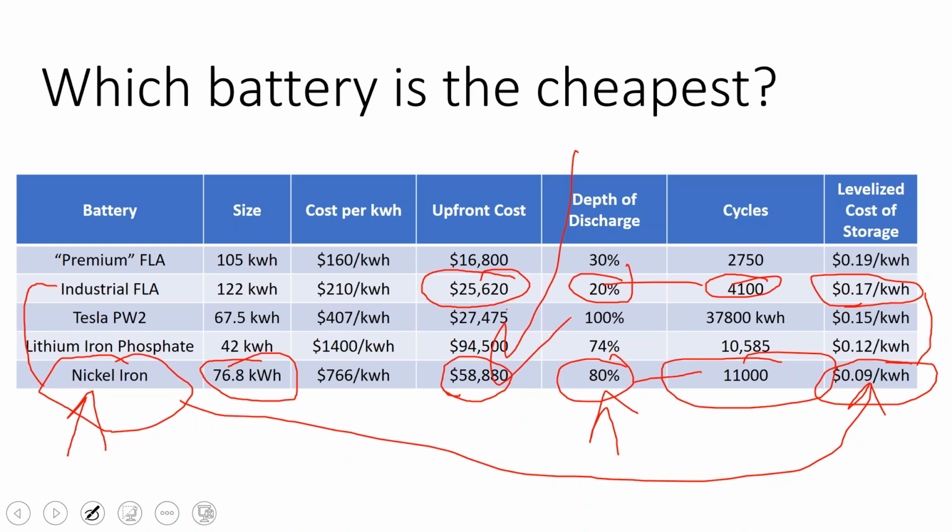And who knows what the battery market's going to look like 15 years from now. It's going to be a lot cheaper than it is today. And so maybe if your budget's strained, going for a 30-year battery may not be the best strategy. It might be that you do the battery that you can afford, and whether that's a 4-year battery or a 10-year battery, what's important is that you get a payback that's underneath the battery life, and then swap out the batteries over the years to come.